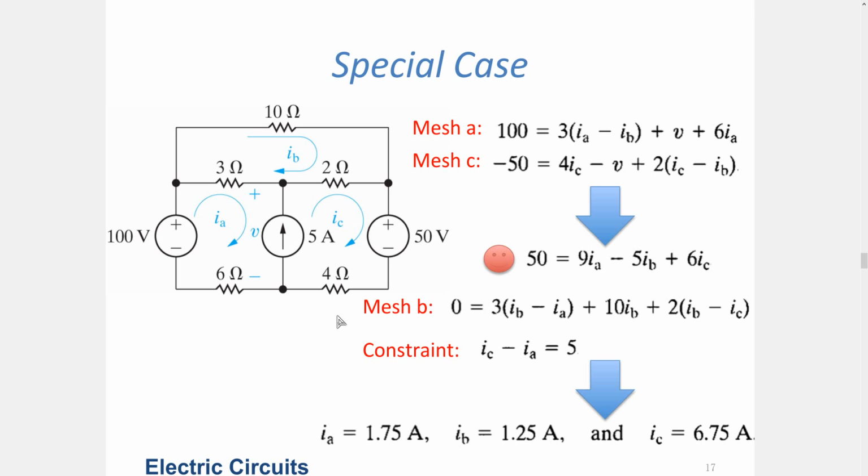At times, it could be useful because sometimes if the circuit has many nodes, the number of meshes can be lower than that. So you may prefer the mesh current approach to obtain a smaller number of equations from the system.